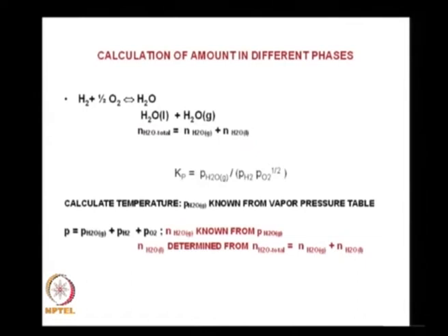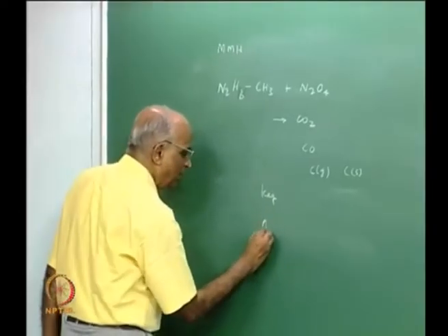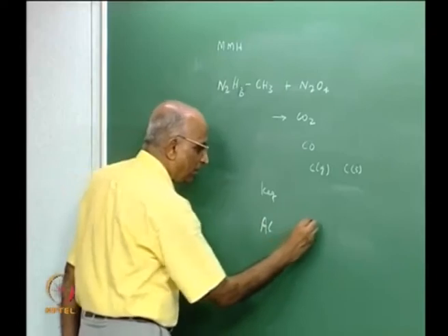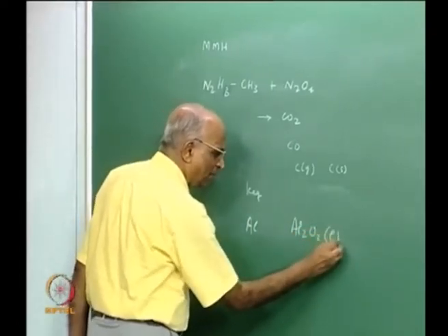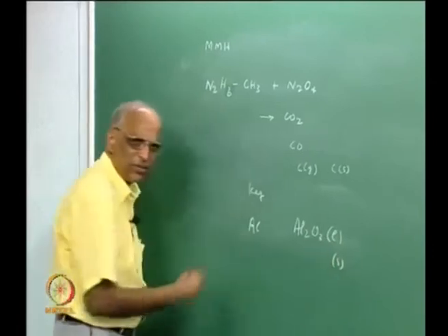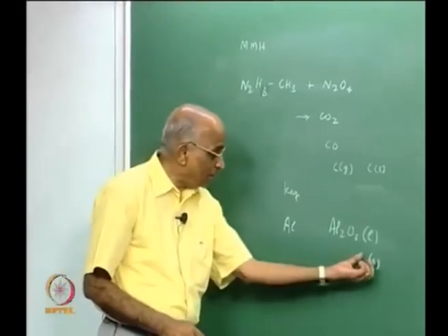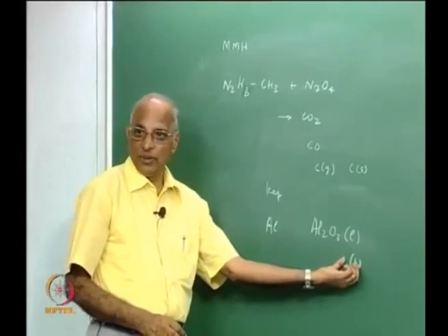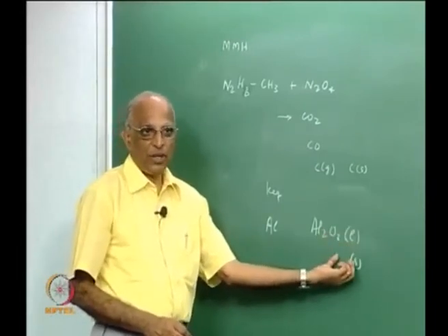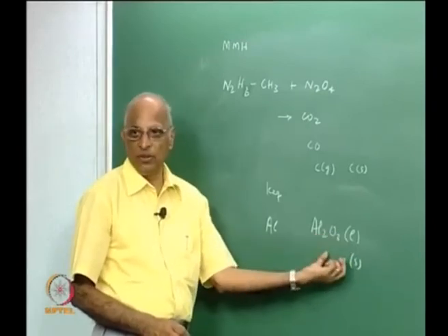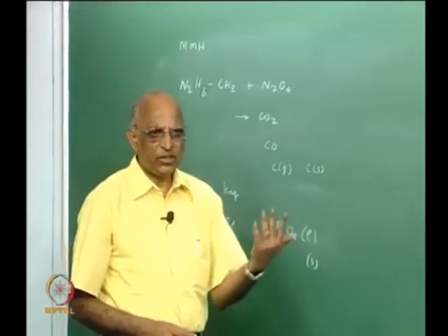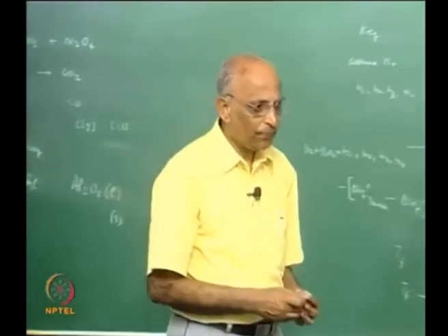And this happens especially when we have solid propellant rockets. I will consider solid propellants in the next class again. We add a lot of aluminium. Aluminium forms Al2O3, and this Al2O3 could be in a liquid phase, could be in a solid phase when it is coming out, and all these things have some energy in them. Therefore, we must be able to calculate this, and those of you who do a project using solid propellants must be able to differentiate it. But the procedure is extremely simple.